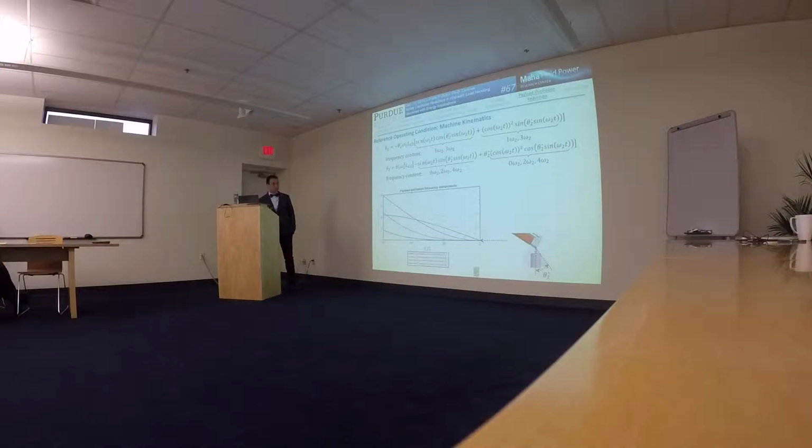And we can see how these frequencies are actually also present in the experimental measurement. Here, this is an FFT of a pressure sensor measured experimentally, and we can recognize again 1, 2, 3, and 4 times the payload oscillation frequency.